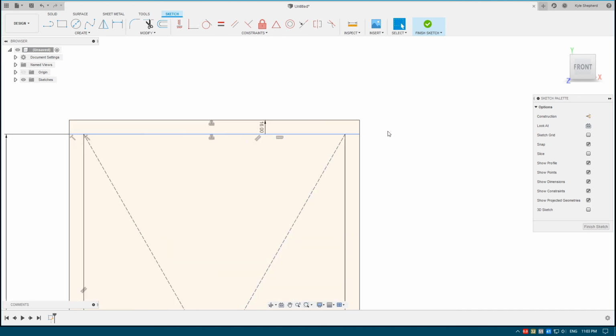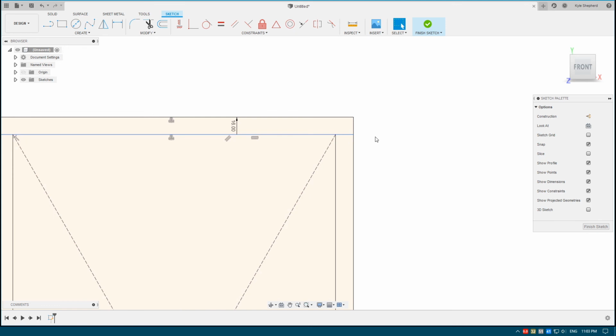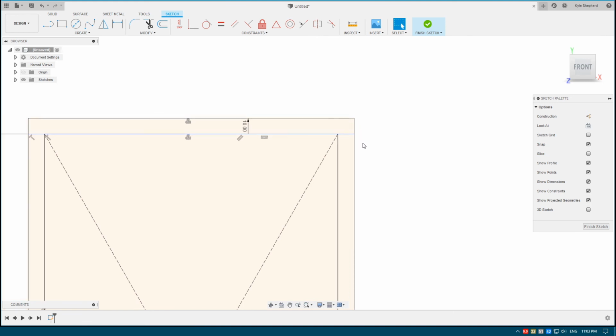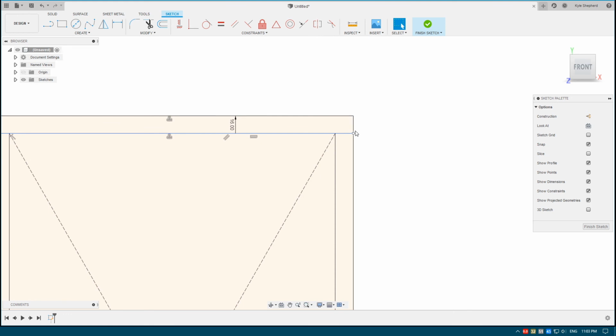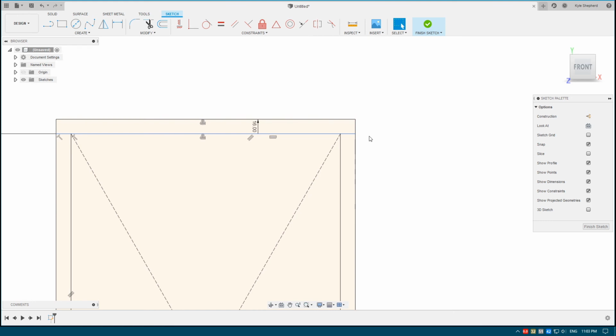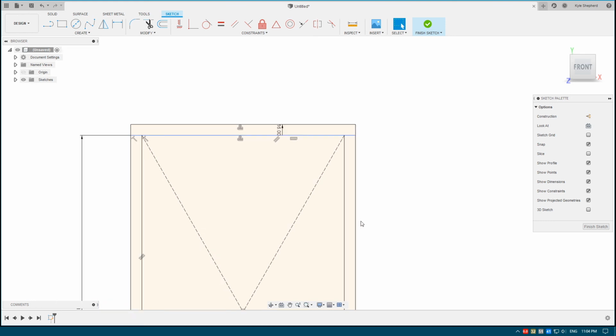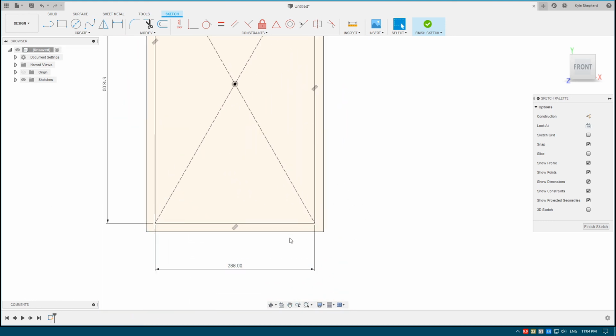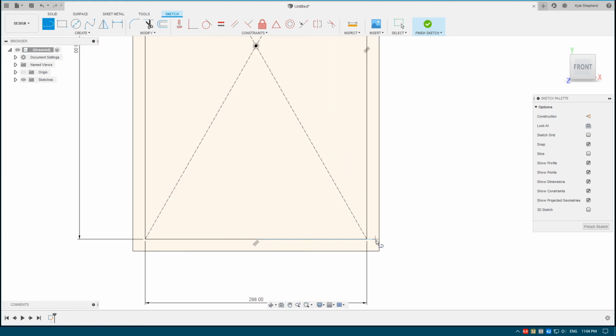But if you're not going to veneer it and just paint the whole thing with a flat paint, then you probably want to do the 45 degree angle, because then you only have to worry about that little corner there, and it'll be pretty smooth. Whereas if you have corners on flats, you're always going to have to bog it up, or really give it a good sand and coating, which I can still do if I can't get enough veneer from it.